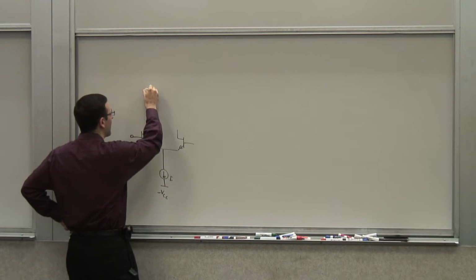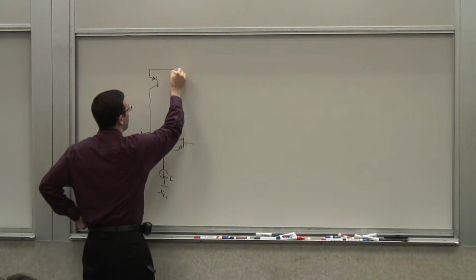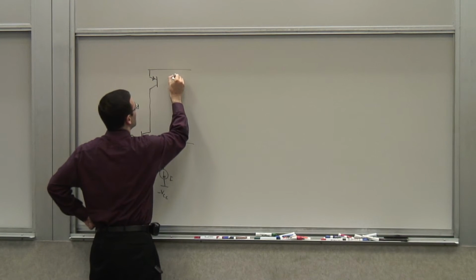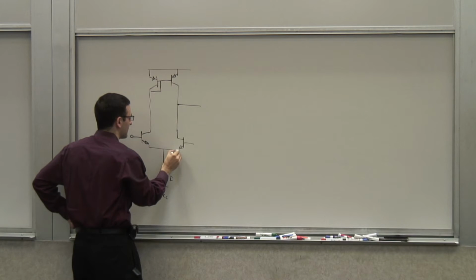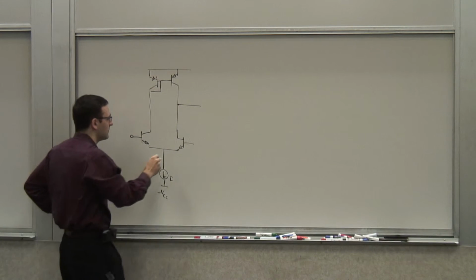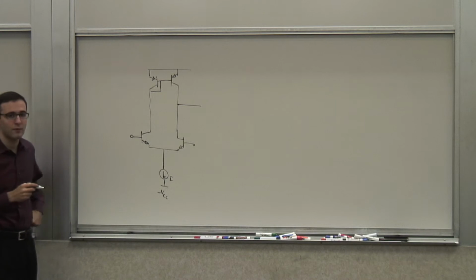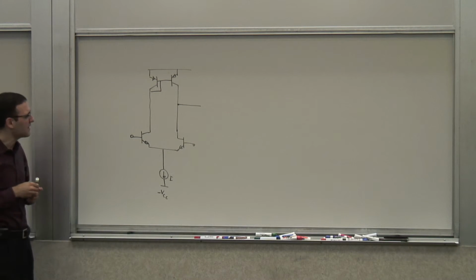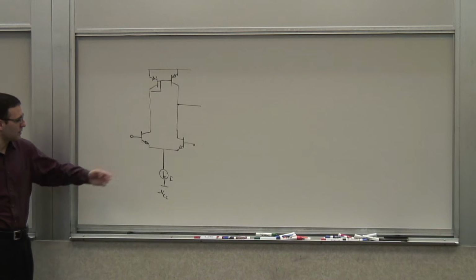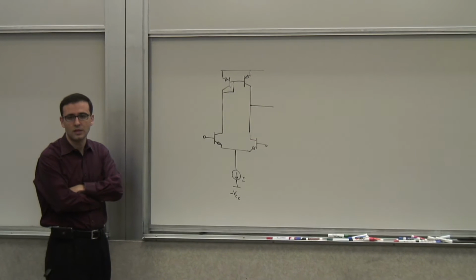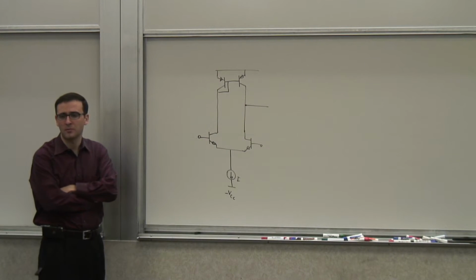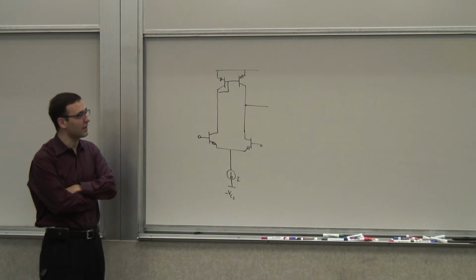And then I know that if I take this differential pair and take its output, and mirror one of the output currents and reflect it to the other side, I get something like that. Okay? Now, let's see what the gain of this thing is. Well, first of all, I have to see what bias current I have to use. Is there any limitation on what kind of bias currents I can use here? Do any of those design specifications that I gave you limit the minimum or maximum current I can use? Think about Rin.